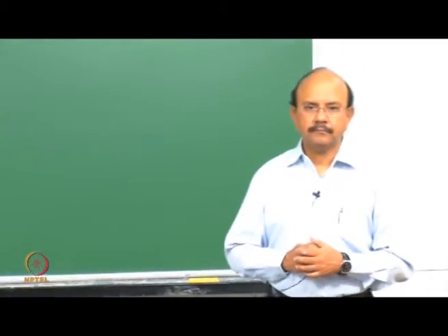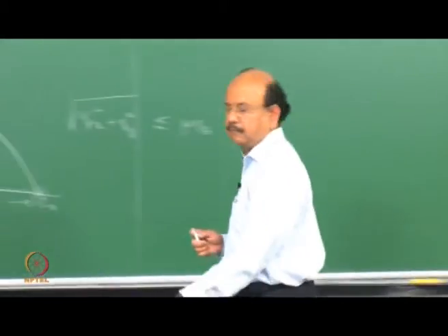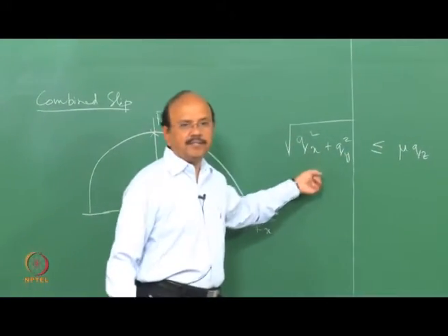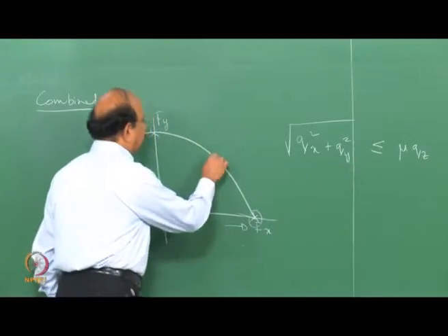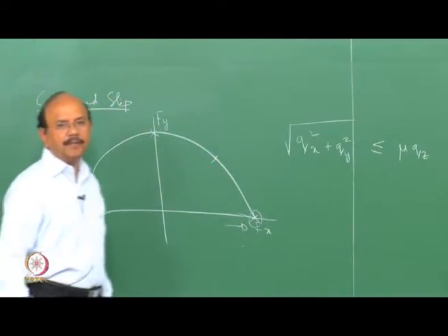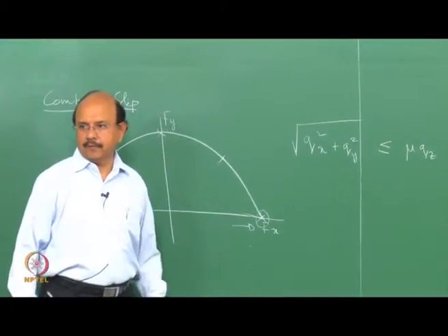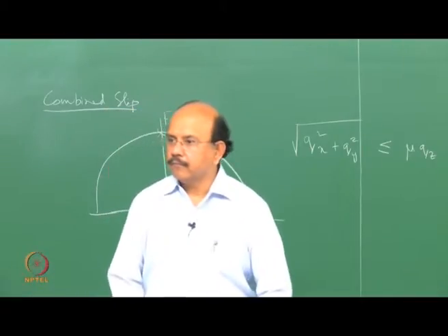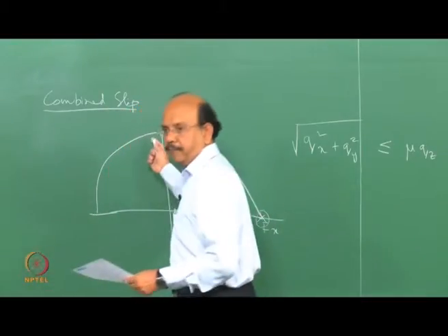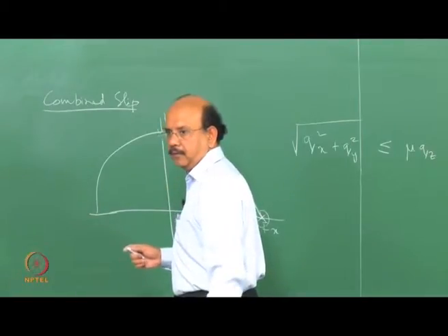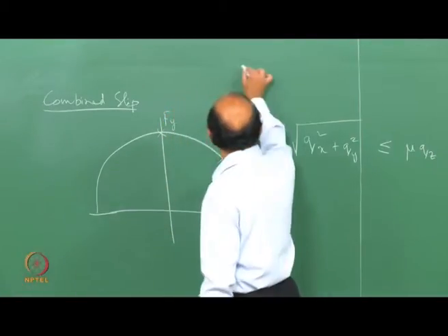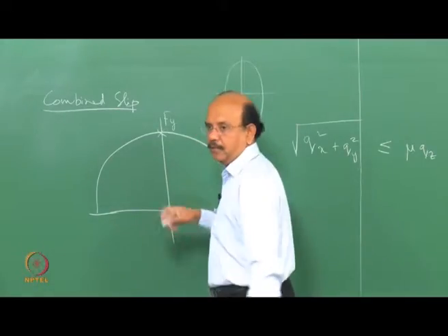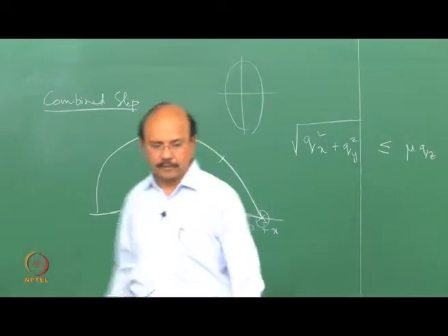So this implies that the boundary, the mu Fn value, is different for Fx and for Fy, because the way it is shared is different here. So ultimately, if you are doing both cornering and braking, that is the type of forces that you would generate. This is the Fx and Fy. See, this is an ellipse like this. I'm putting only one part of it.